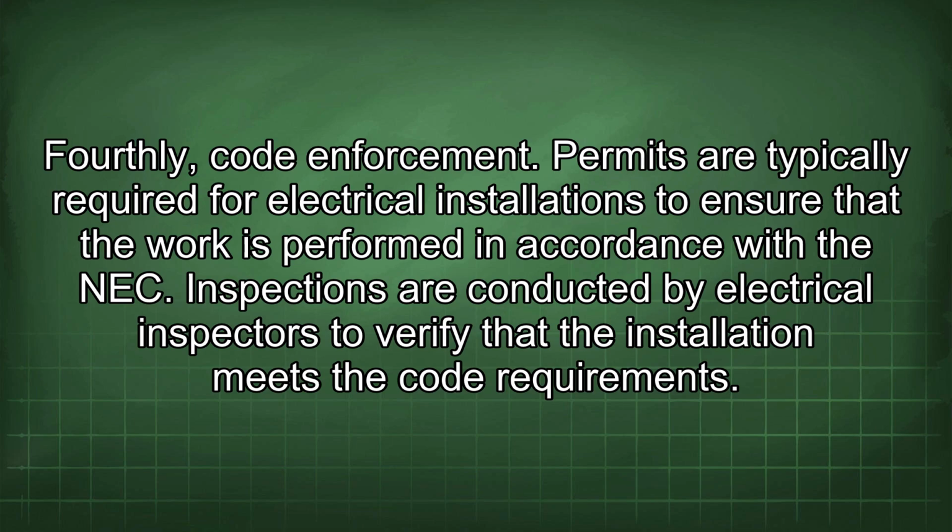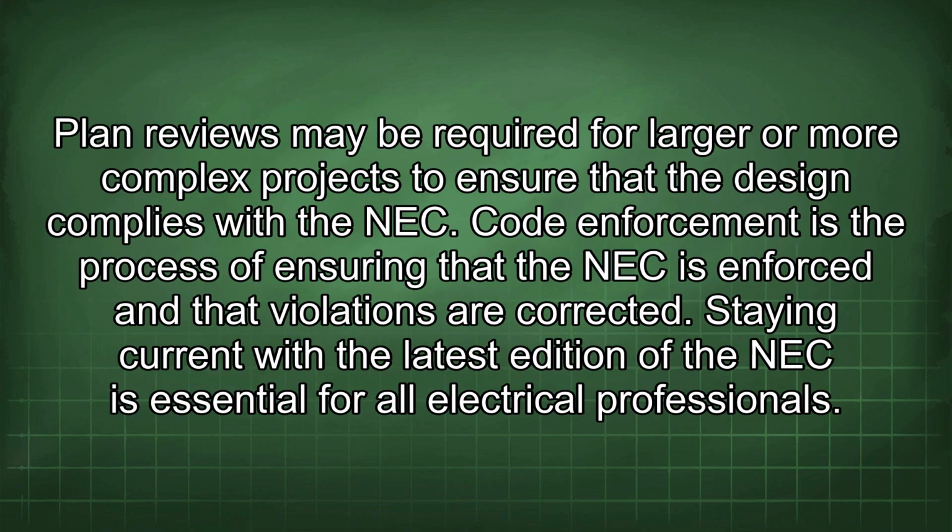Permits are typically required for electrical installations to ensure that the work is performed in accordance with the NEC. Inspections are conducted by electrical inspectors to verify that the installation meets the code requirements. Plan reviews may be required for larger or more complex projects to ensure that the design complies with the NEC. Code enforcement is the process of ensuring that the NEC is enforced and that violations are corrected. Staying current with the latest edition of the NEC is essential for all electrical professionals.